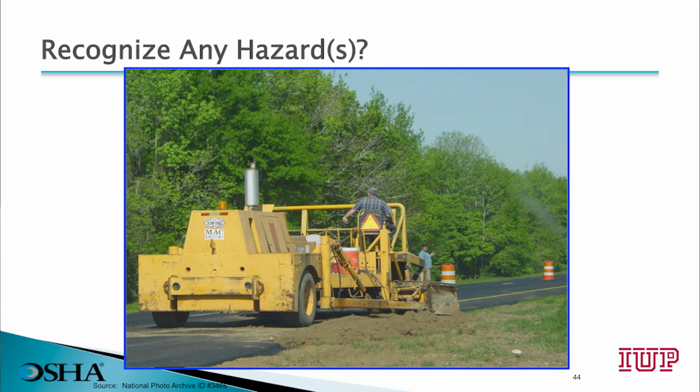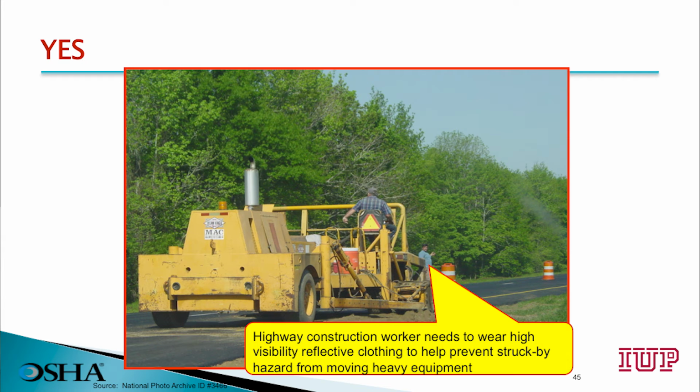Can you recognize any hazards on this job site? Here we have a highway construction worker who needs to wear high visibility reflective clothing to help prevent a struck by hazard from the moving heavy equipment.